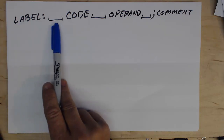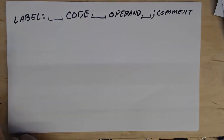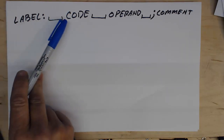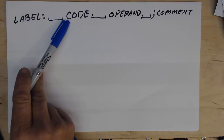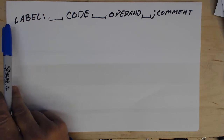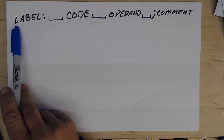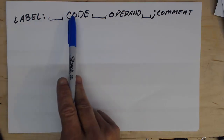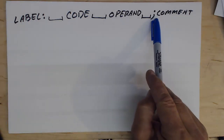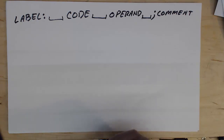The white space can be any number of spaces or any number of tabs, so there's no restriction on that. The assembler will probably require that the label starts in column 1, and it will require that the code starts in any column other than column 1. Just put your labels starting at the very left side in column 1, and then when you're writing code, at least put in one space before that. Other than those requirements, the assembler is fairly lax in terms of the syntax, as long as you're using a valid code and the valid number of arguments in the operand, and you use your semicolon, and after your semicolon you can use any character you want in the comment until the end of the line.